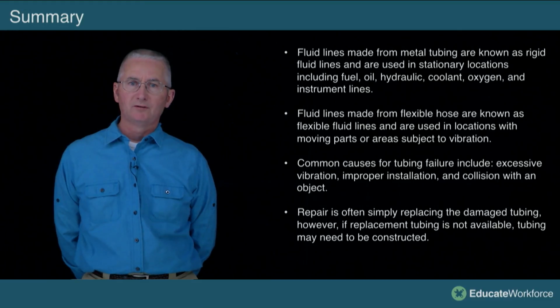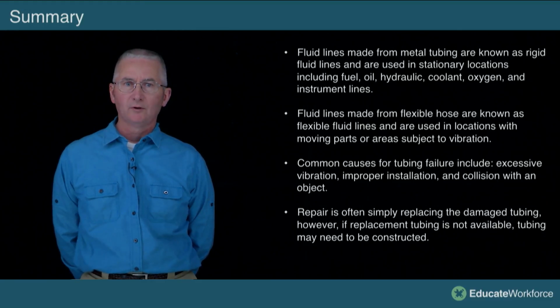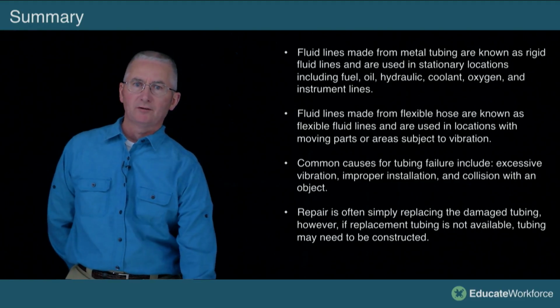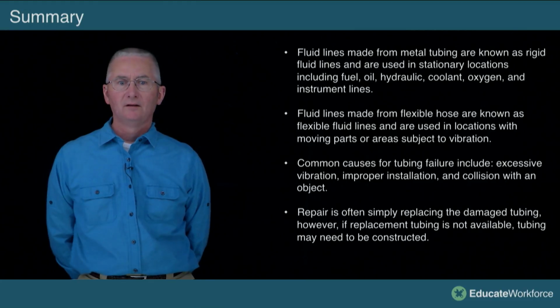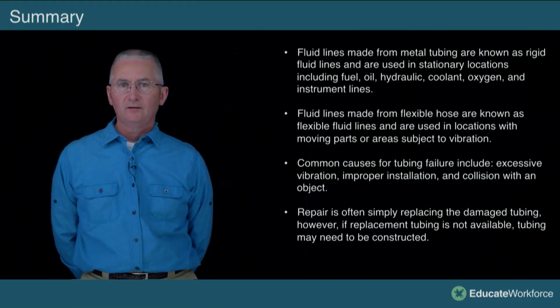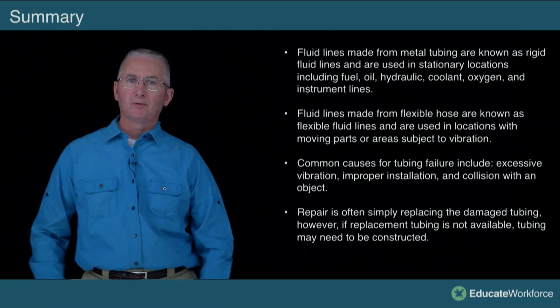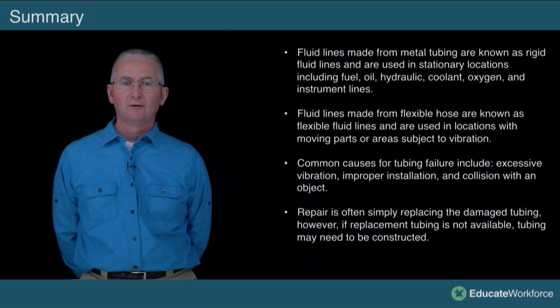Obviously, fuel is going to be significantly cooler than hydraulic fluid. It's going to determine the pressure. Your instrument lines are going to be very low pressure, whereas your hydraulic lines are going to be high pressure, 3,000 psi. The flexible hoses, again, still can handle the same pressure, but we're going to use those in an area where we have excessive vibration or we have a component that's moving.